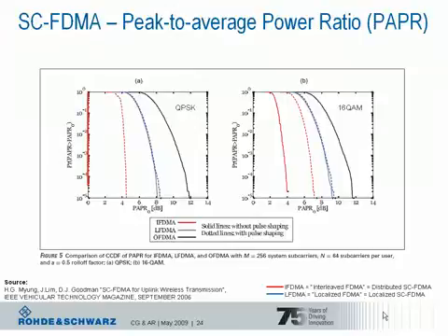The simulation uses a system with 256 subcarriers in a 5 MHz channel, where 64 subcarriers have been assigned to the user, which are in case A QPSK modulated, and in case B 16-QAM modulated. Further, pulse shaping was applied to the signal or not.